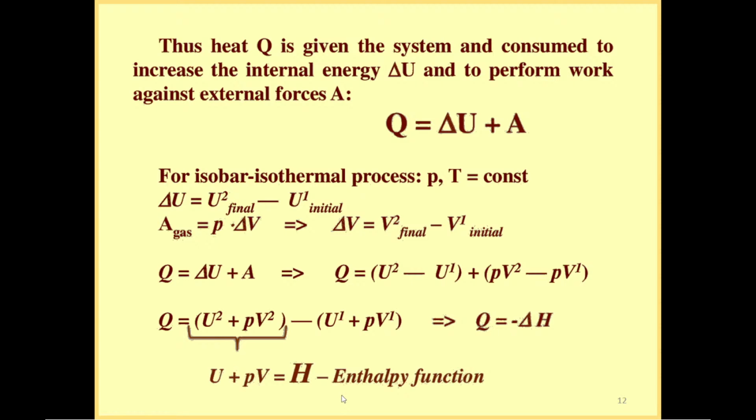So, when we talk about the transition from one state to another, we talk about the change of internal energy. But at particular conditions, as in this case, we can introduce one more function of state. It is the enthalpy. And the first law of thermodynamics we can rewrite by that means as: the heat that is supplied to the system equals in its magnitude the decrease of the enthalpy.